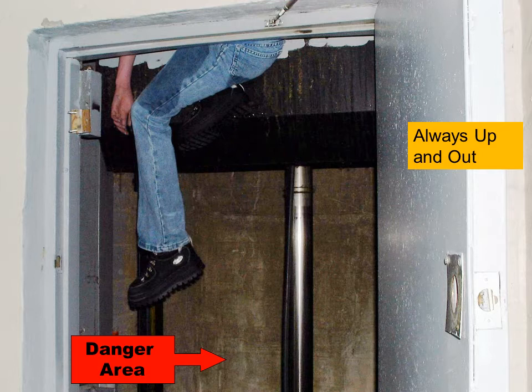The term up and out refers to the removal of any victims inside an elevator car. Always try to go up and out rather than down and out. If you must go down and out, you will need to barricade the open shaft to prevent anyone from falling in.